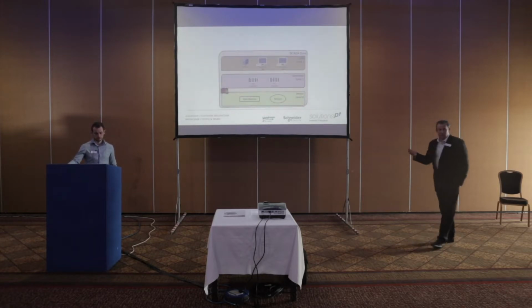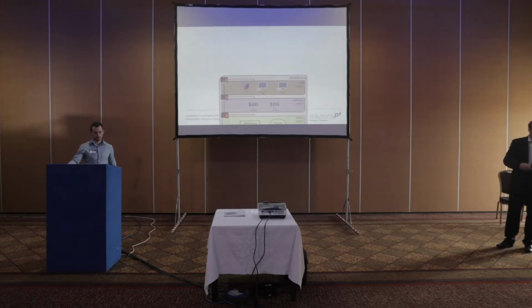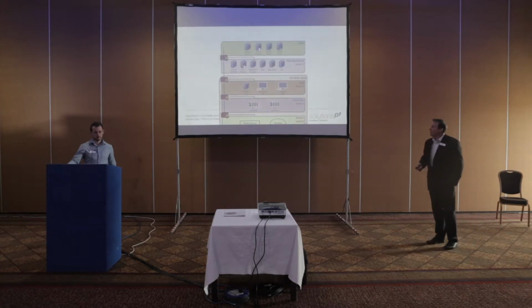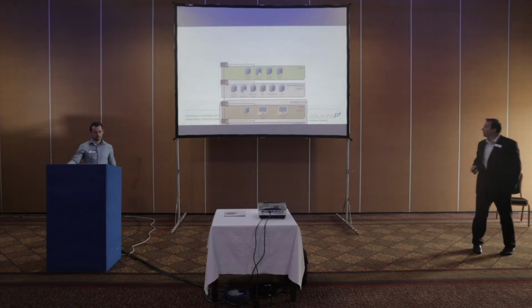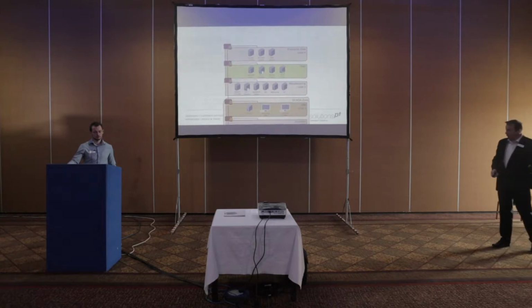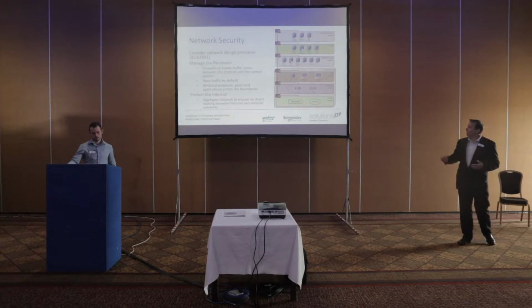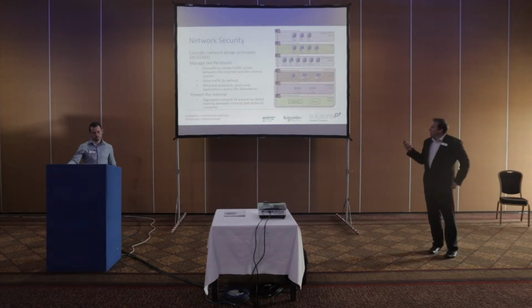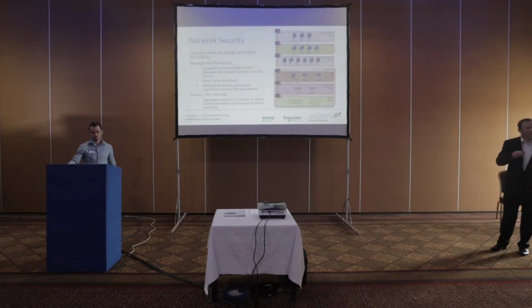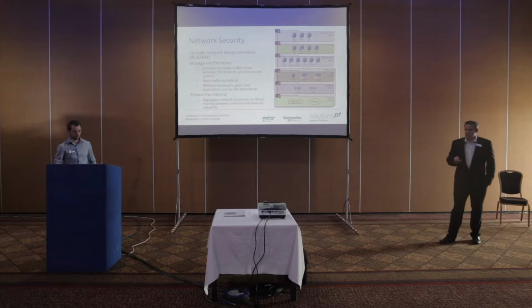So if I just put up a typical architecture, one that we've seen before with our instruments, PLCs, and SCADA, moving up into our MES level, through a DMZ, and finally up to an enterprise layer. So this is essentially taken out of guidelines from 62443, where we start talking about zones and conduits. But when considering your network security, it is best to start with the guidelines that we can see within the ISA 99, IEC, ISO standards.